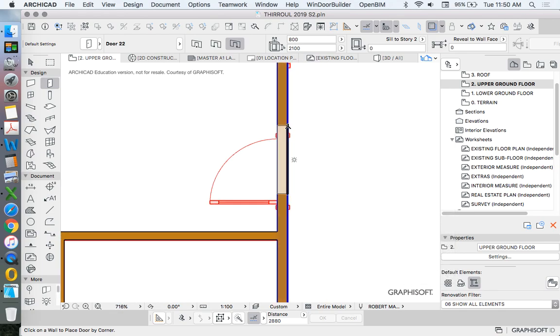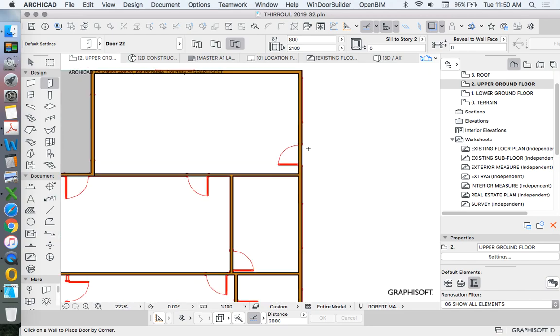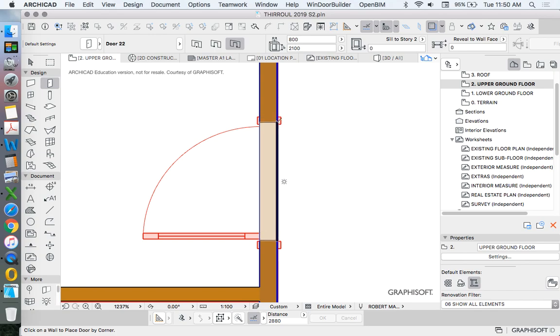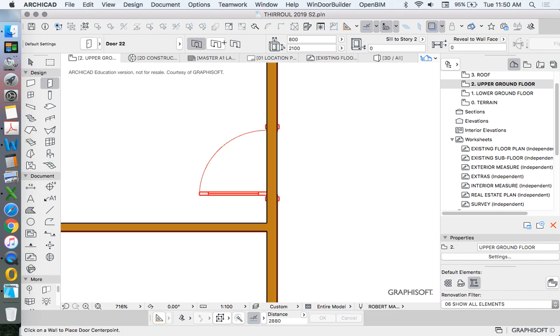When we place it, we have to click somewhere. So we can see here at the moment, we're clicking or hovering over the screen in order to place the door. And if we flip side, it would choose from the different end, or if we choose middle, of course it will be based on the middle. I would suggest that it's not that important, and it's quite hard to get this in the right place at the right time. So if I chose endpoint, I need to align it here. I need to make sure it gives me this intersection point first.